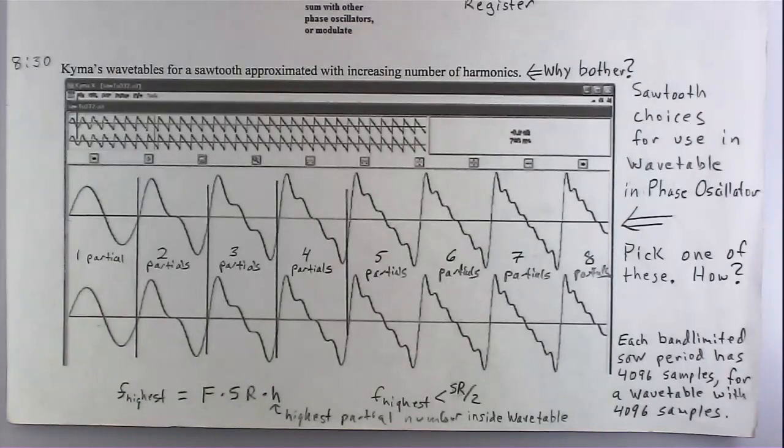But there's other weird things you're going to run into today which don't make immediate sense. Like if you have a waveform that's exactly repeating in analog, well, okay, you can think of a corner case, but it'll never be exactly repeating in digital. And that's weird. And a lot of people miss that. Even very smart professors I talk to just don't think about the practical implication of these things. So again, I'll repeat that. If you have an exactly repeating waveform in analog, it won't be exactly repeating in digital.